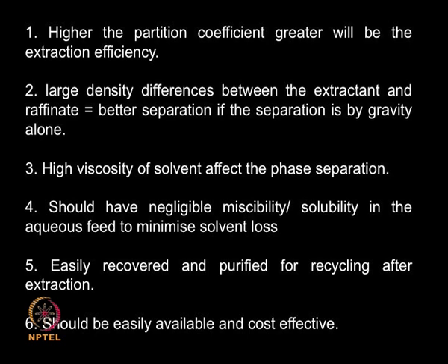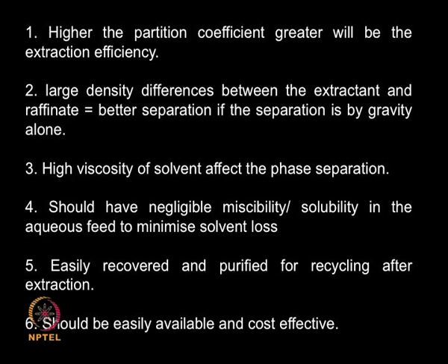High viscosity of the solvent affects the phase separation, because as I said your fermentation broth will be highly viscous because of cell debris, biomass and other proteinaceous material which have come out of your broken cells. So the movement of the solute from the heavies into the light is very slow. Next point, there should not be miscibility of the solvent into the heavies and vice versa, otherwise you are losing some of the solvent into the heavies, which is lost actually. So the idea is you have to minimize the solvent loss.